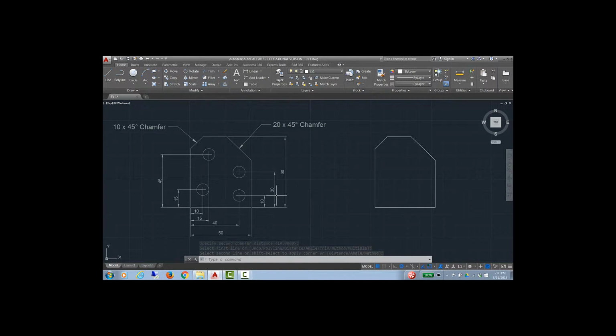Next, we're going to create the 4 circles on this exercise here. It may be counterintuitive, but what we're actually going to do is create the circle on this bottom left hand corner here and then move it the distances that we want to go by typing in the coordinates. So let's begin. This circle has a radius of 5, as we can evidence by the 10 millimeters to here and 15 millimeters to this dimension line that touches it.